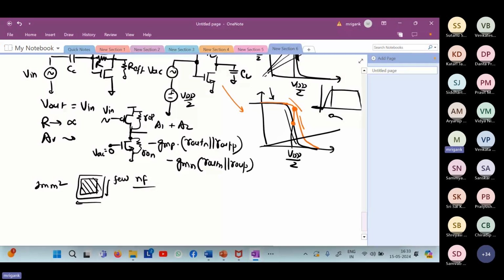You can understand that overall the coupling capacitors that we can use in circuits on chip will be much smaller. They will be of the order of picofarad or femtofarad region, a fraction of a picofarad. Generally we may have 50 femtofarad, 100 femtofarad, 1 picofarad, around that kind of value. So on-chip capacitor values are limited to these values. We can't use very big capacitors.